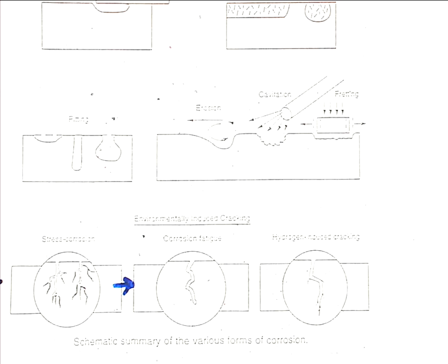Under flowing conditions, the corrosion rate is a bit faster, and if the flow is actually impinging on the surface of the anode, so instead of just being a flow past it, parallel to the surface, if it's actually impinging on the surface in some way, either directly onto it in terms of flow, or because it's a pipe and it's got a bend in it, and then you get impingement on this surface here, or because you've got a defect in the pipe, like the root of a weld, that causes some turbulence, then you would get an impingement in these places here.